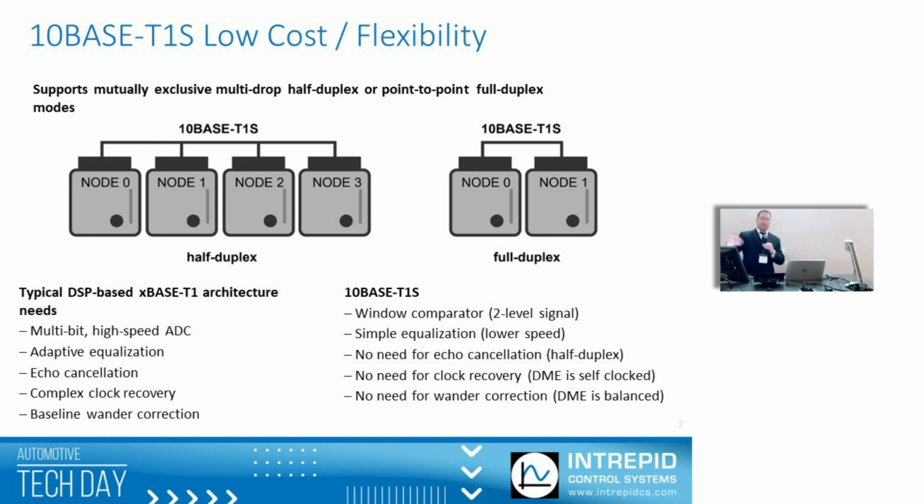Therefore, if you want to hook this to a switch, you can, but you just have to have the right PHY for that, a 10BASE-T1S PHY. So instead of, for example, node 0 there on this picture, that could be a port of a switch. And it works fine, because you can have a single port of a switch with multiple MAC addresses connected to it. So this is just like the scenario where you have multiple MAC addresses connected to a single port of a single switch. It's identical, it's no different.